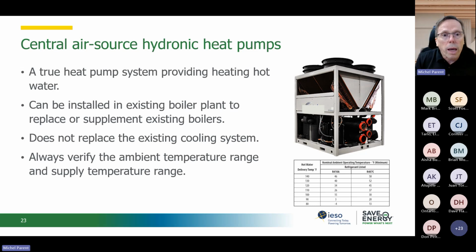The internal gain is what heats your return air, which is what is used for the chiller because they cool the return air before it goes back to the building. So if you move away from that, and now I'm not using my internal source as my heat source, you will use the outside air as your heat source, just like a residential heat pump.